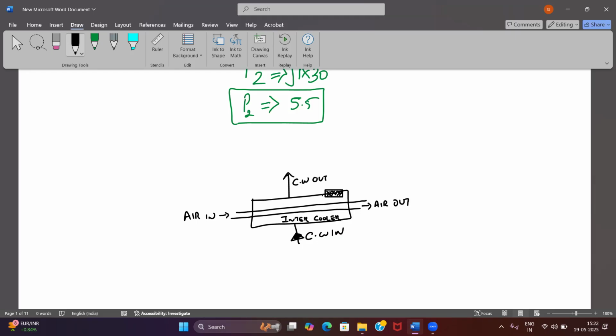All right. First of all, let us see the pressure at which this bursting disk is going to burst. It should not burst at the cooling water pressure. Do you agree? Yes, sir. Because water pressure will always be acting on this bursting disk, as it is mounted on the water side.